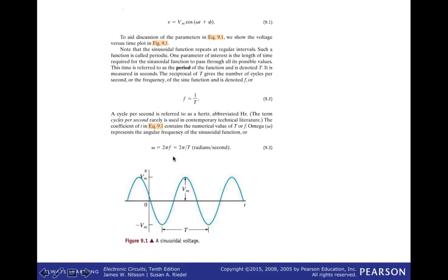So first of all, when we talk about AC circuits, we're talking about circuits to which we have applied a sinusoidal voltage. That voltage is usually written in this way, looking at equation 9.1, where you have a voltage expressed as a magnitude, Vm, a cosine function, and I should point out that in order for phasor analysis and all of the applications and techniques that we use regarding phasors to work, the voltage has to be written in terms of a cosine function.